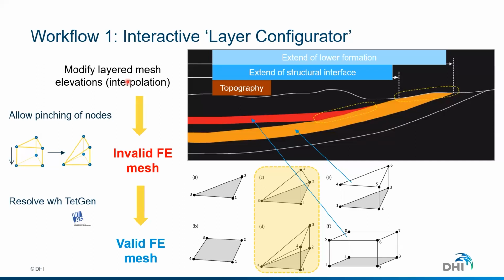So now, by introducing new methods in FEFLOW, we secure the possibility to build 3D unstructured meshes. The most simple option that you have is via the layer configurator. This is a workflow that everybody who works with FEFLOW should know, where you have point data, and using this point data, FEFLOW can interpolate using kriging, inverse distance, or Akima methods, and then create a set of different surfaces or slices, what we call in FEFLOW, to construct the structure of the model.